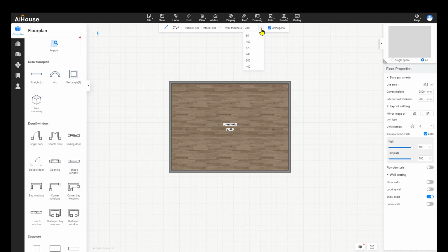During the drawing, you need to know that you can left click to confirm the start point and right click to disconnect or end the command. And now you can see the first wall. I can left click to confirm this wall or input the wall length. Like I would like to input 5,000 and hit the enter key. Then the wall will be set.